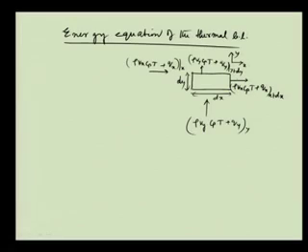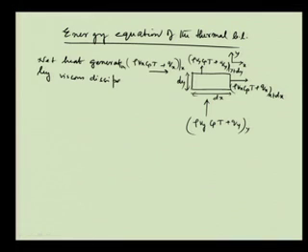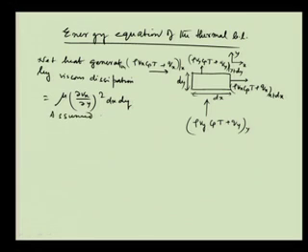And then the net heat generation by viscous dissipation is mu into del V x by del y, whole square, dx dy, and we will assume this to be 0.